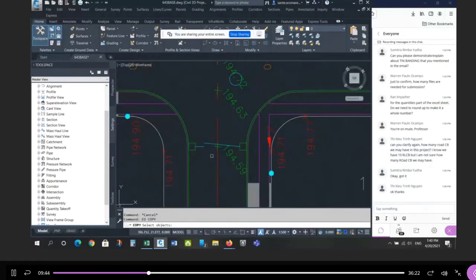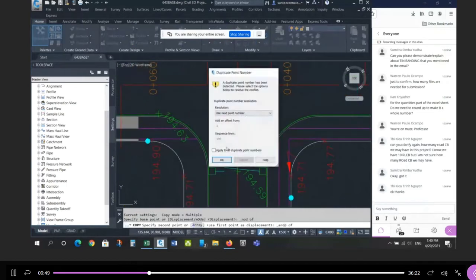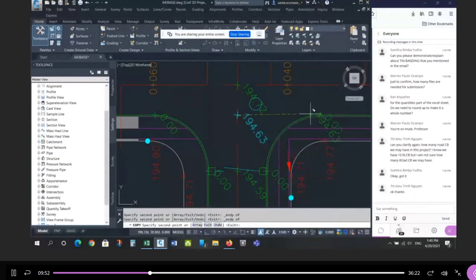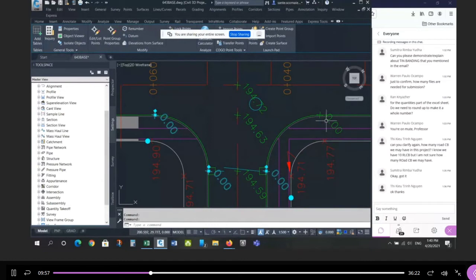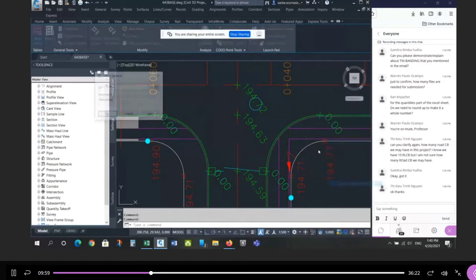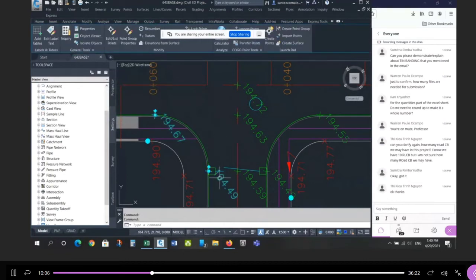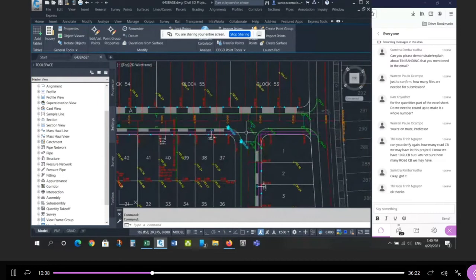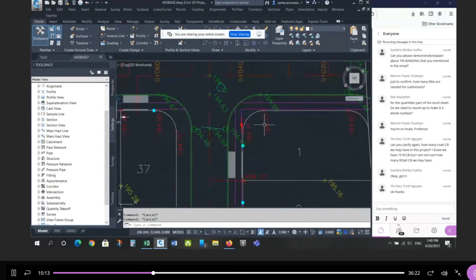Okay, same thing here, watch. This is one of the discussions we haven't had, and again, I don't have time to teach everything, but let's take a look here, and here, and here. So if we look at these 4 elevations, elevations from surface. These come from the corridor model. You'll see water falls from here to here, right? All the way along the road to here, and then from here coming down. So this is receiving water from long stretches from both sides.